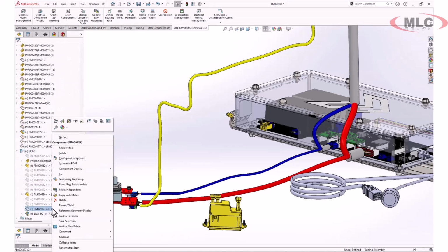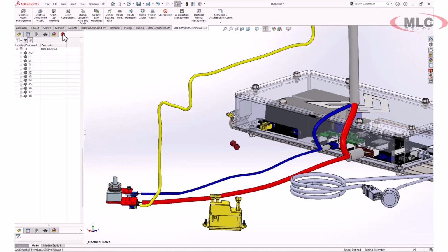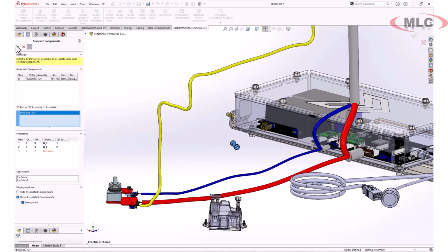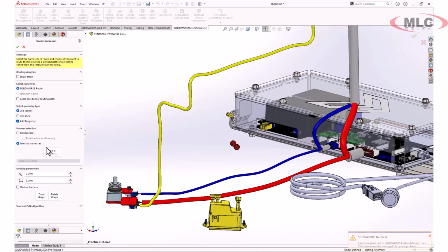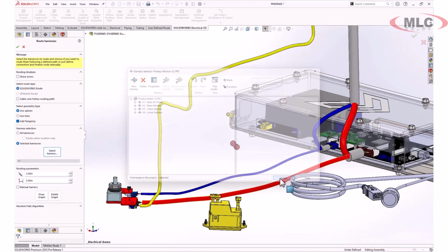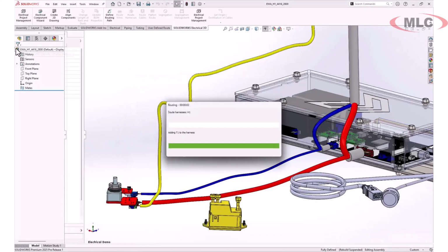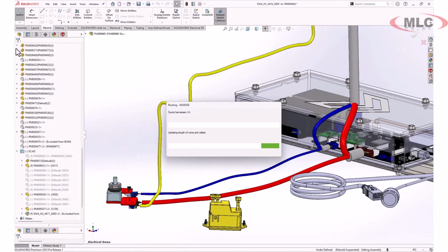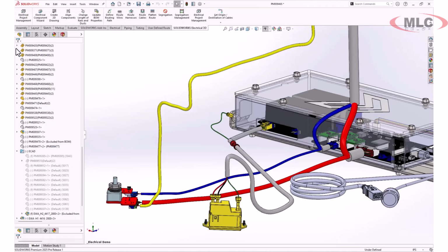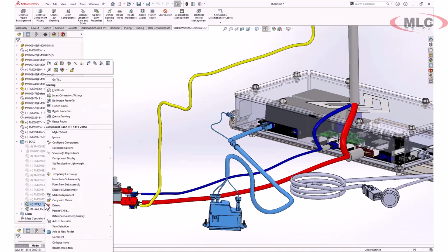There's my new splice, and it's right on top of my EW path sketch, so all my wiring will be routed through there in one entity. In 2025, Flatten Route now prevents creation of a loop when there's a splice directly on top of the path. SOLIDWORKS now uses existing sketch segments passing through the splice component instead of adding a new sketch segment for the unspliced wires, which avoids creation of a loop at the splice component.